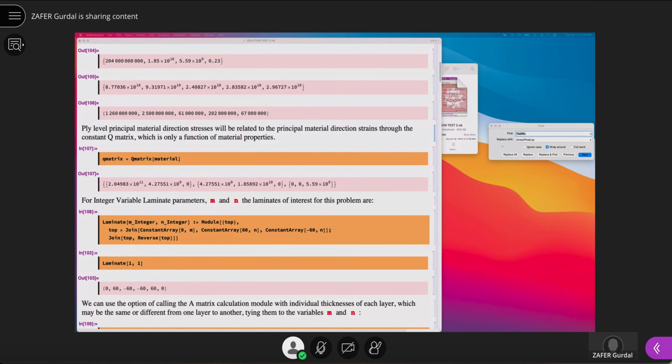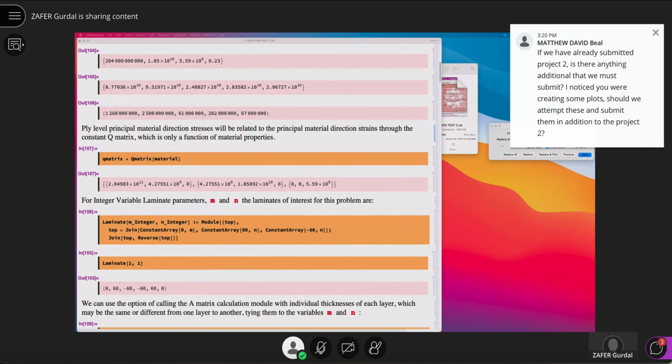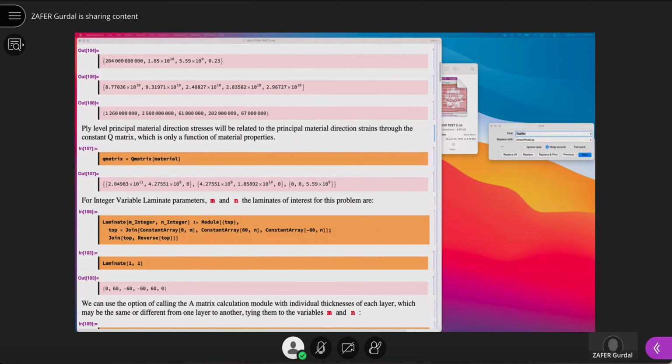But it's just another analysis that gives you stresses. Just like having sigma 1, sigma 2, tau 1,2 in a given layer, you will also have stresses between layers that will have some measure of separation between them, and that will become a constraint in the process.